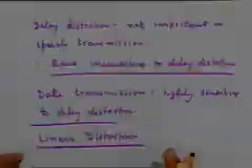One important characteristic of linear distortion is that the existing frequency components of the message signal get treated differently by the channel, either in terms of their attenuation at different frequencies or in terms of delay at different frequencies. One nice thing about linear distortion is that, at least in concept, it is very easy to compensate for, isn't it?